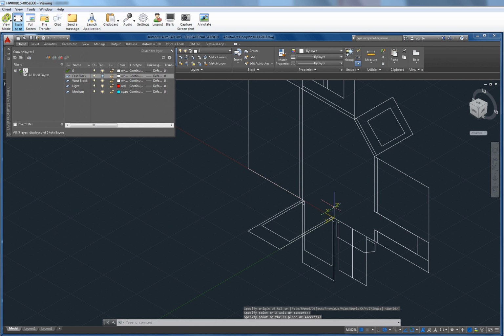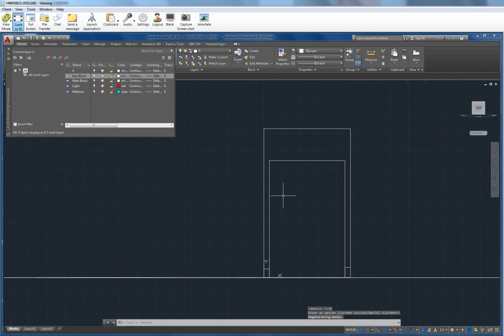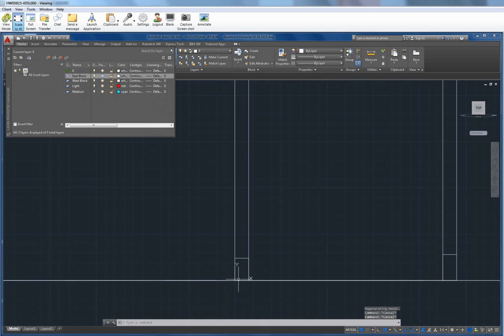Because the Z, like where we draw now, so if I go back to plan now, nothing will change. But now I know my UCS is actually at that surface position by moving it. You put coordinates in. So Z0 now is on the wall. Because otherwise, if you're drawing and Z is over here and you're thinking you're drawing here, this was happening with some of you on the detail. The line work was showing up over here. Yeah, that's kind of what my question was. Yeah. So we have to reorientate. So that's the tricky part.